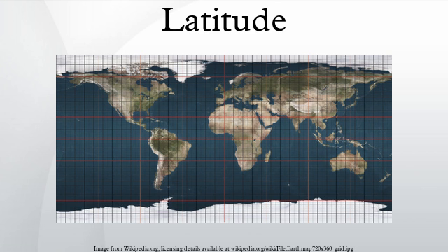Numerical comparison of auxiliary latitudes. The following plot shows the magnitude of the difference between the geodetic latitude and the auxiliary latitudes other than the isometric latitude. In every case, the geodetic latitude is the greater. The differences shown on the plot are in arc-minutes. The horizontal resolution of the plot fails to make clear that the maxima of the curves are not at 45 degrees, but calculation showed that they are within a few arc-minutes of 45 degrees. Some representative data points are given in the table following the plot.